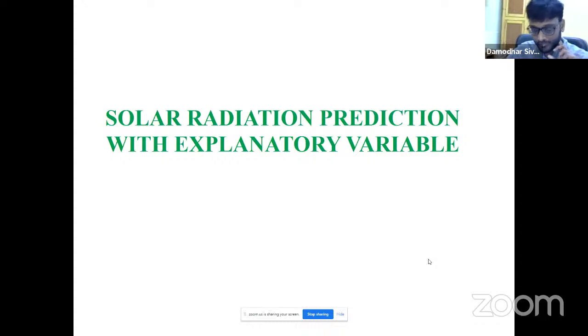A solar panel has a glass which is transparent in nature. The glass has to allow the solar photons into the panel, then only the photons will be absorbed by the semiconductor and electrons released by the solar PV panel. So if there is an obstacle to the solar radiation reaching the panel, such as dust, it also has an impact on the solar power output.